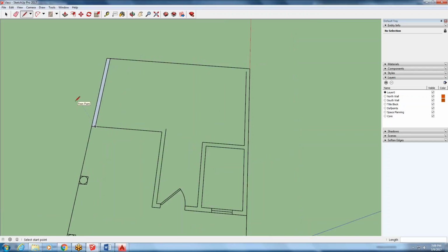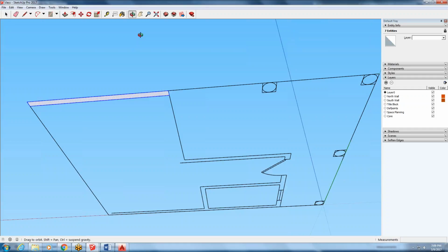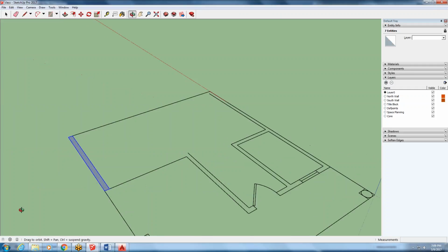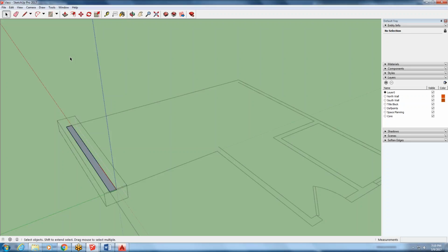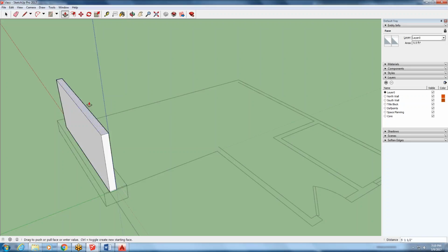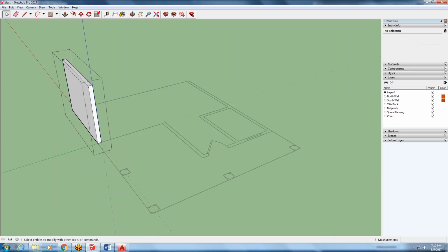We're going to have to delete a few interior things in order to separate these out into nice clean groups. So now when I triple click though, will it try to take the whole model? It still does. So okay, if I triple clicked and made sure I was only on that. I just want to triple click it until it only gets that, and then I want to make it a group. Okay, then I double click to get into that group and I can modify just that wall. Type 8 foot for the height, and there's my first wall for your homework assignment.